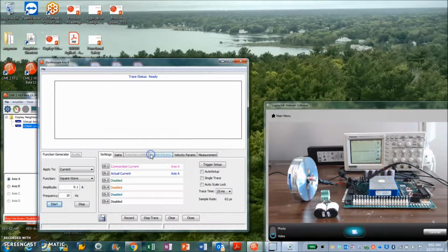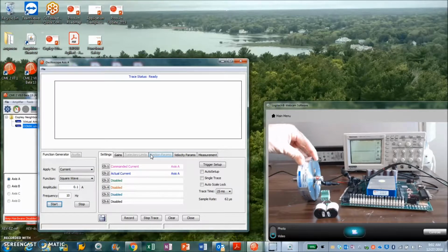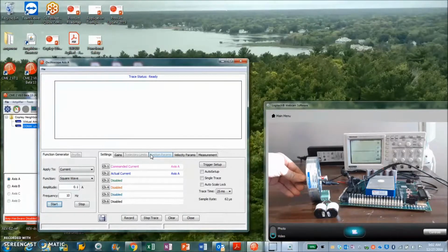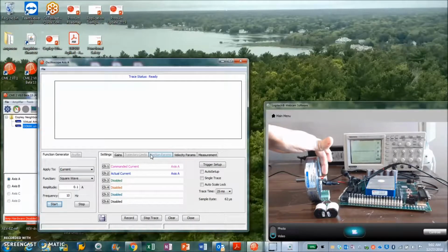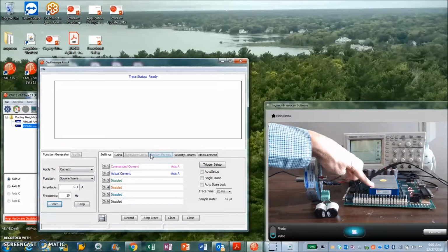So what we have here is the Pancake motor. It has a shaft in the back and the front for the load and a typical encoder. We're going to run it today in open loop velocity mode or current mode. You could put a feedback device on the load and close the position loop that way, running this in the back EMF mode. But typically we see an encoder on the shaft of the motor. It's extended out the back for that. And then you could have dual loop with a Copley Plus drive.